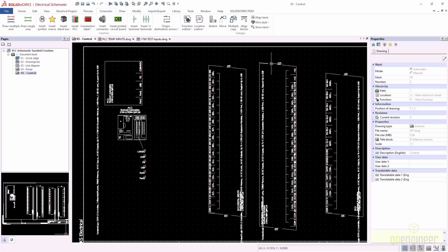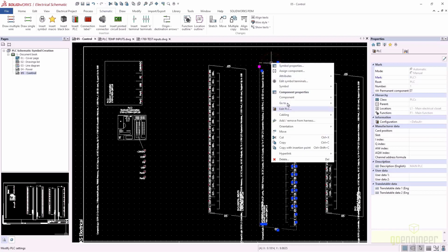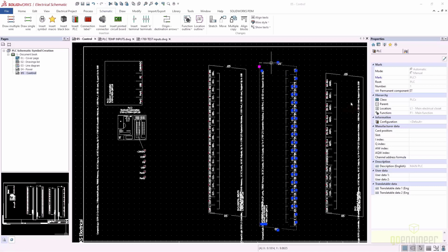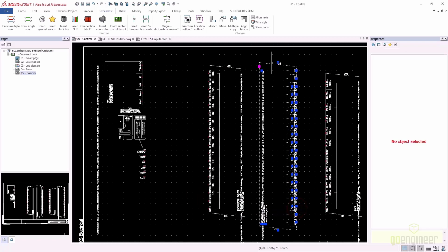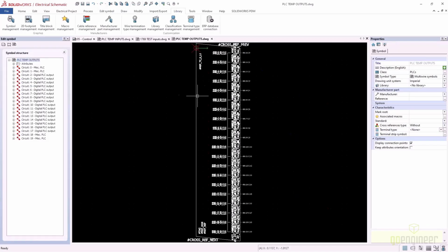All right. Let's go ahead and make a temporary symbol from the digital output, so that way we can verify how these circuits are working. Highlight everything here and make our temporary symbol. Once you get used to making some of this, it will become a little bit more fluid for you because you're always doing kind of the same thing. So here, let's just double check that our connections are set up. It looks like we've got miscellaneous PLCs on the top and on the bottom.